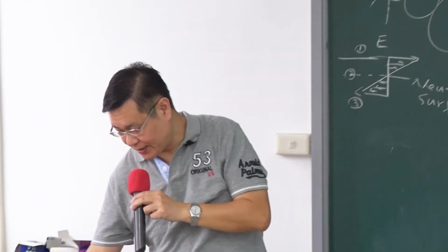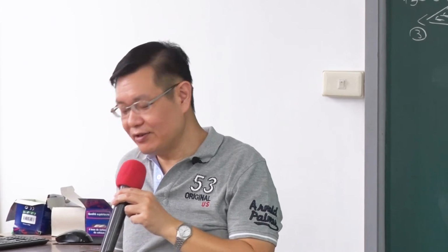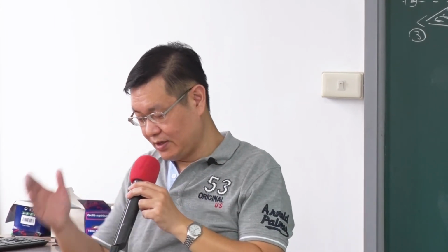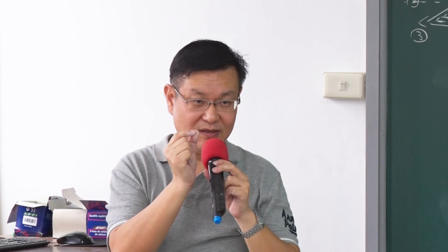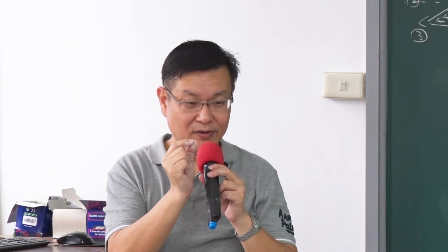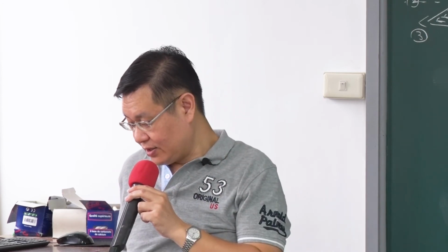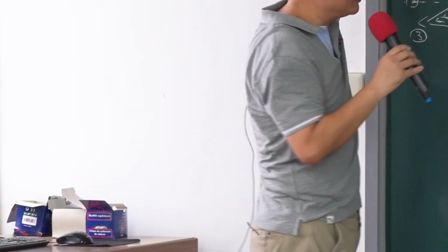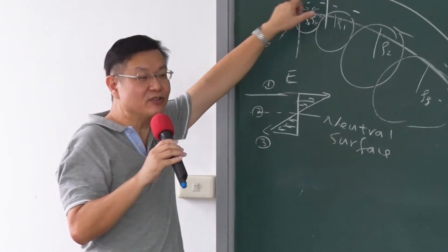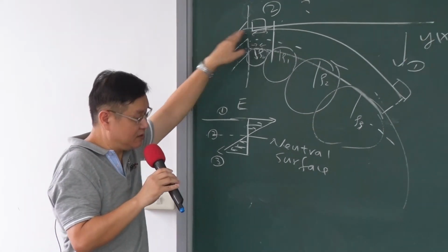The bottom equation gives the average strain along the surface when your sensor has a finite length, not a single point. The equation comes from adding the top and the bottom values divided by 2. That's it. Just average across this surface.